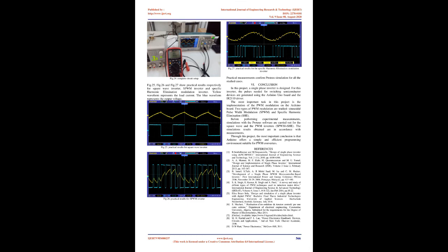C. Specific harmonic elimination modulation, SHI. As explained previously, the specific harmonic elimination modulation consists in determining a set of switching angles in order to eliminate certain harmonics in the PWM inverter output. These angles are obtained from MATLAB by resolving the system in equation 14. The switching angles, shown in Fig. 9, are injected in the Arduino code in order to generate the SHI modulation signal. The following code must be written with the Arduino software, IDE.